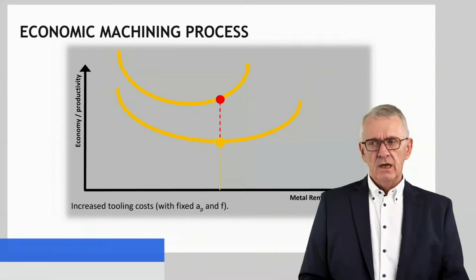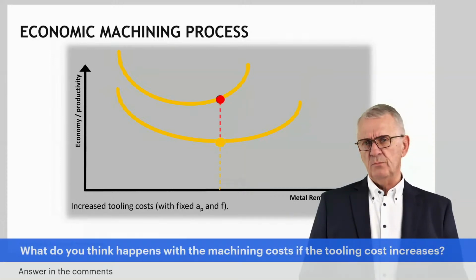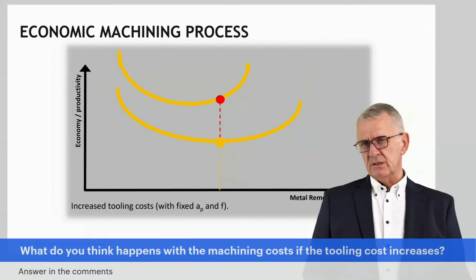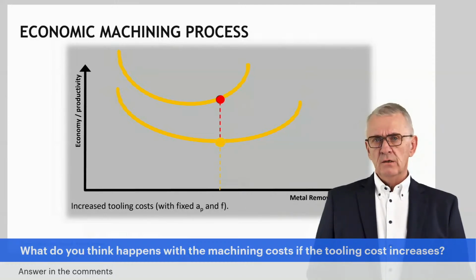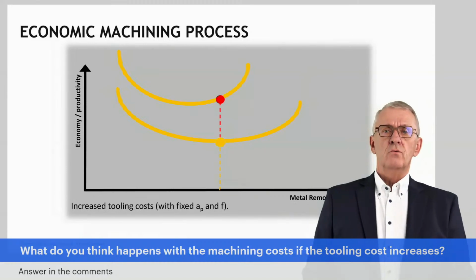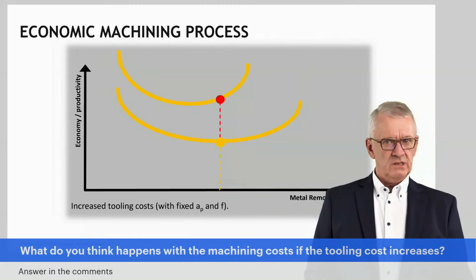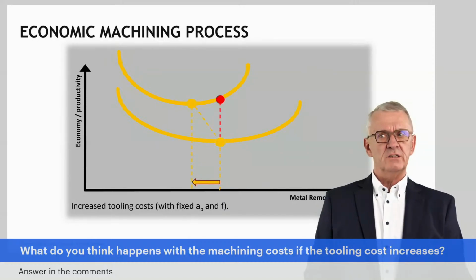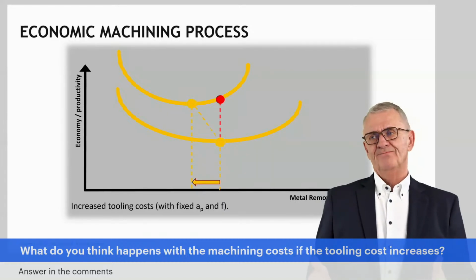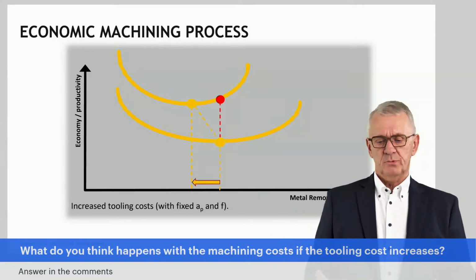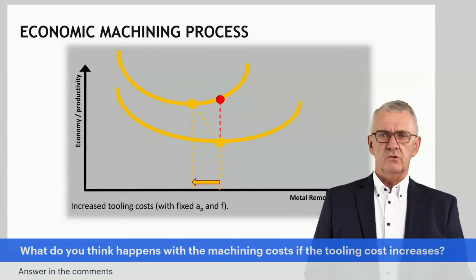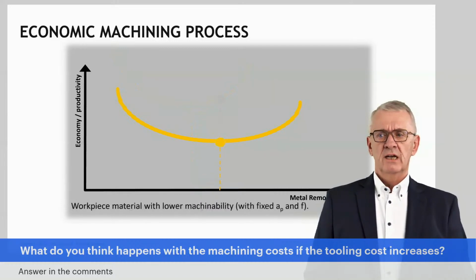Yes, there is. And again here, it's very strange, because normally people think, if tools are more expensive, I should increase my cutting conditions so I use my tools more efficient. No! When we talk about costs, and that's what we discuss here, if you are confronted with more expensive tools, you should reduce your cutting conditions to compensate, at least partly, for the increased costs. And perhaps you have some problems here. It's strange. Again, I invite you, let's stay in contact here. We can talk afterwards about these principles.